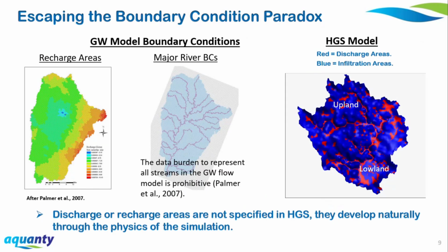So to build on that last point, in an integrated surface water-groundwater model, the recharge and discharge areas are not defined upfront. This is what I referred to at the beginning of the presentation, that the conceptual model is generally simpler for an integrated hydrologic model than for a groundwater-only model. This is how integrated hydrologic modeling escapes the paradox of specifying recharge and discharge boundary conditions.